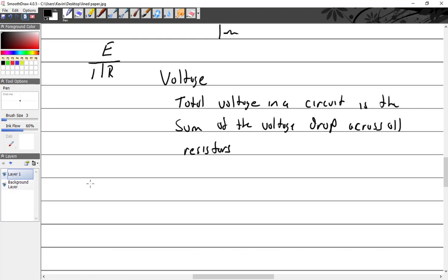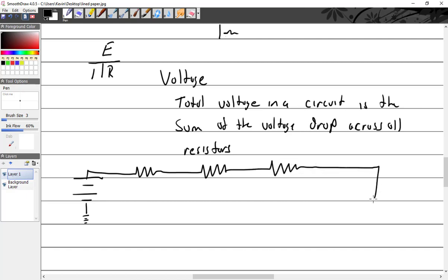That's another way of saying that if I have a battery, some sort of load, and I'll put the little ground there, I've got a resistor, and a resistor, and a resistor. Do I have a complete circuit? Yes, you do, because wherever you see these little ground symbols, that means there's a path, I'm just not showing it, that goes all the way back around. Maybe if it's in an airplane, it's just a big wire that's bolted to the aluminum frame here, and this wire is bolted to the aluminum frame over here.